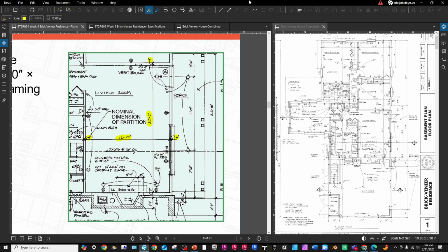So you'll also see it where they go face of drywall to face of drywall. You'll also see that. One thing to note is also just look and read any notes on the plans just to confirm what the architect's intent was, if it's going to face a stud, which more likely is going to be on the framing plan, or if they're going to face the drywall. Great question.